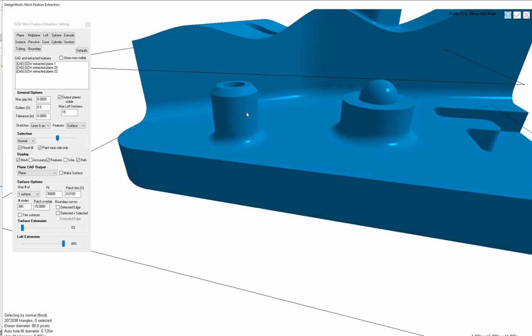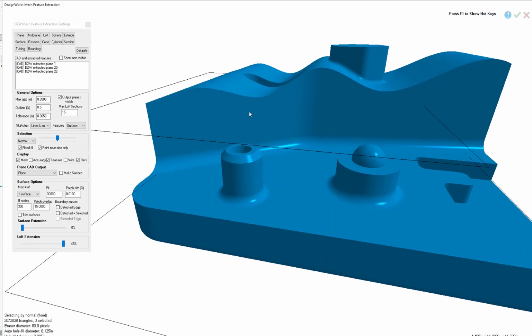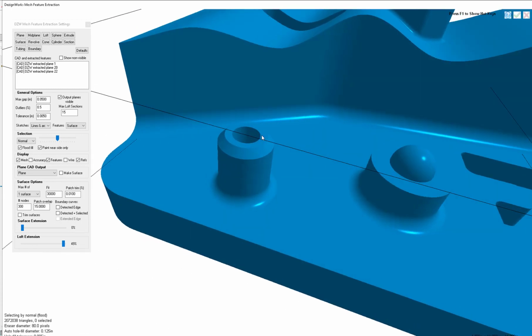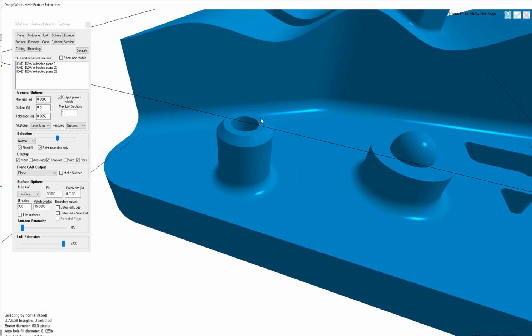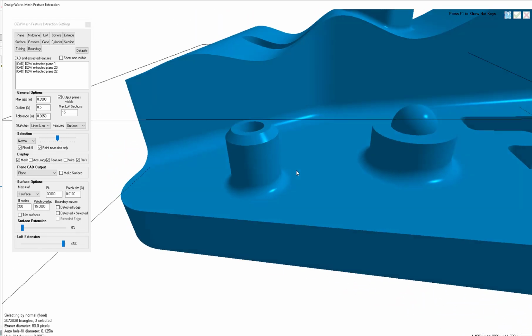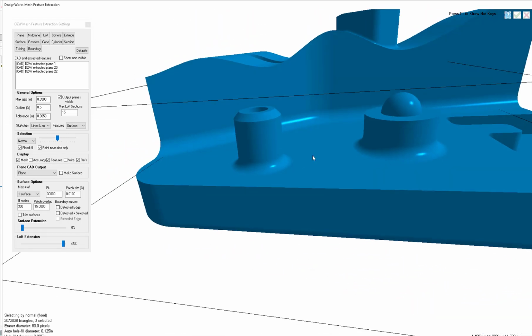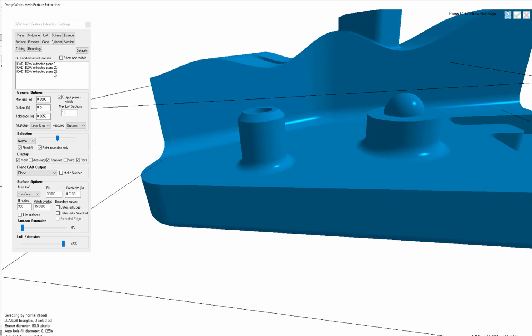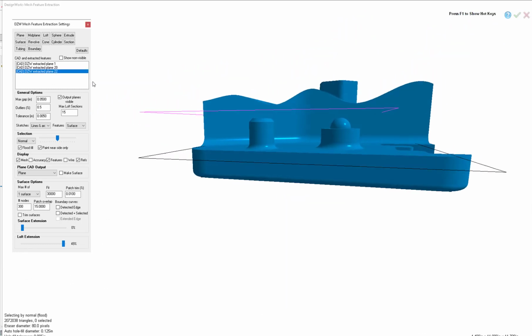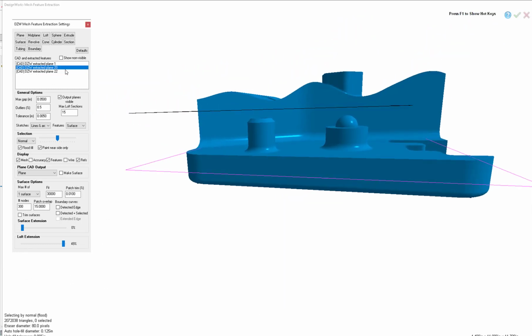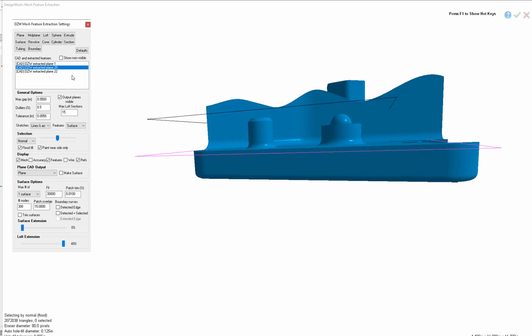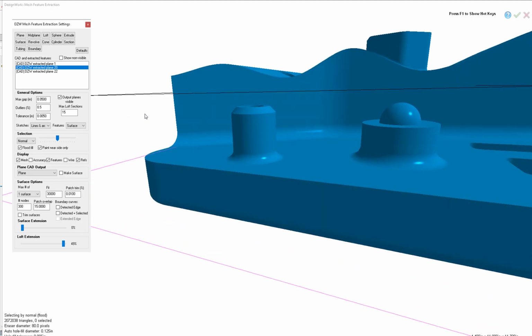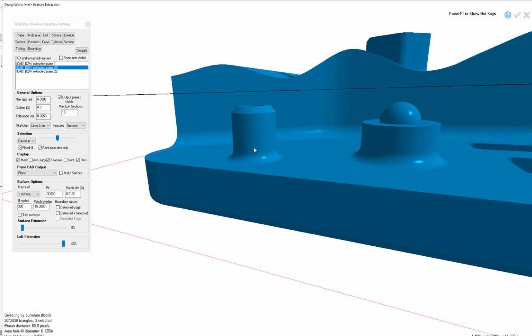So here, we're going to go ahead and just build a plane, either could be on the top or the bottom. So let's say you wanted to actually make it constrained from the top. You could do that. Or we have an existing plane here we could already use. So if you click on these, you'll see where they're at. That's the one we had on top. Here's the one there. So we could use that one. We could say use that as a constraint. And we do have a tool called curvature. It's either C or curvature.